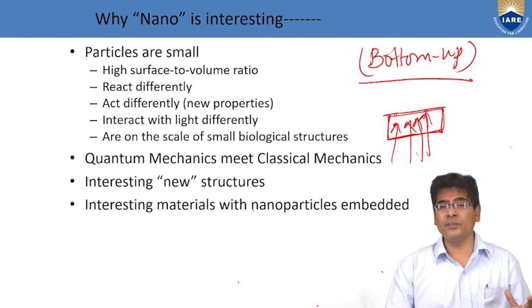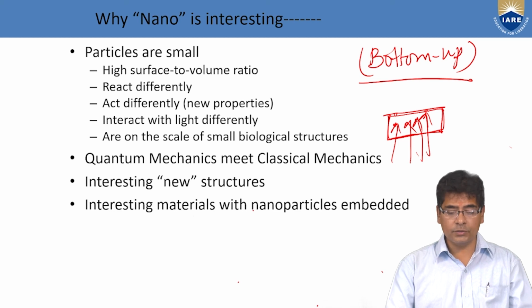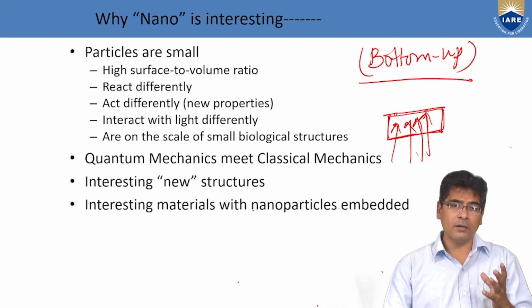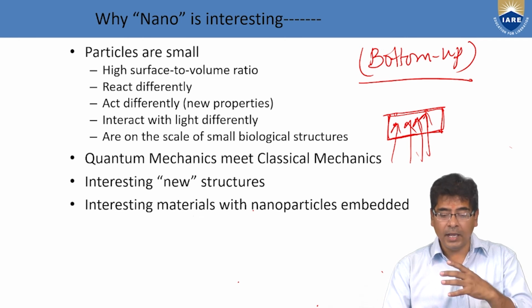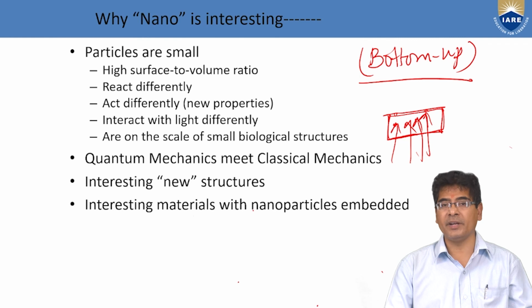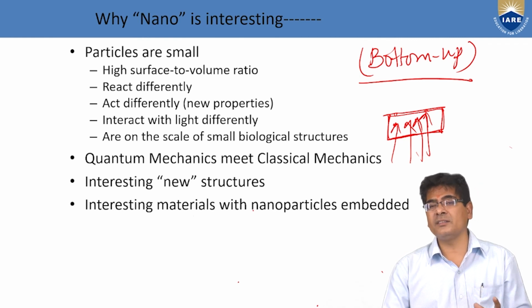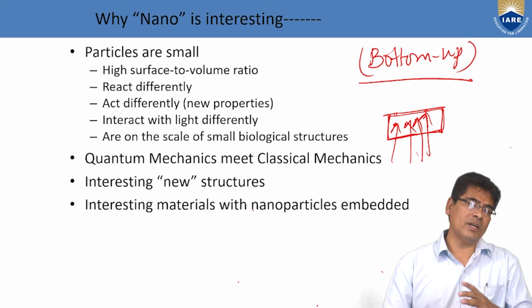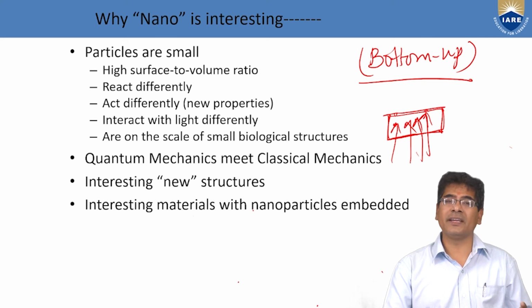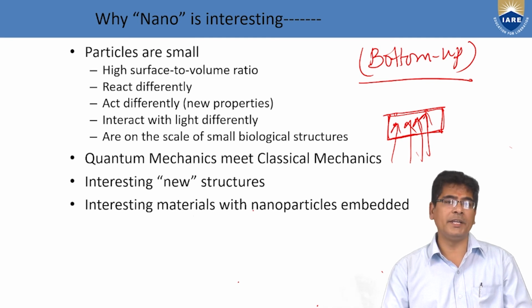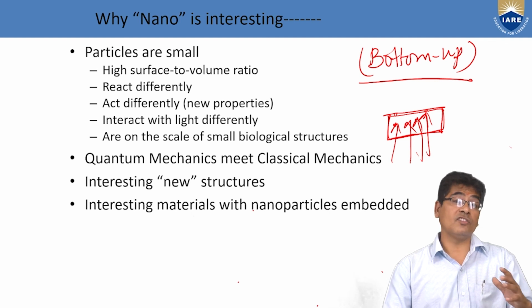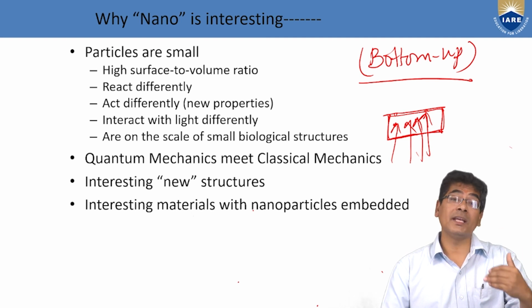PVD is a process used to convert a solid material into gaseous material by some physical process, which is then cooled and redeposited on the substrate as per the requirement, considering the phases, the pressure, the temperature, the gas, and the flow rate while depositing a solid material onto a substrate.